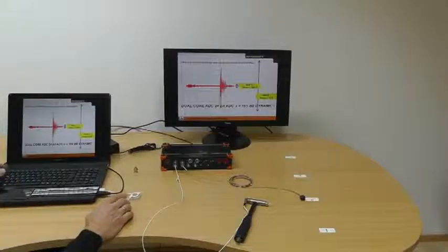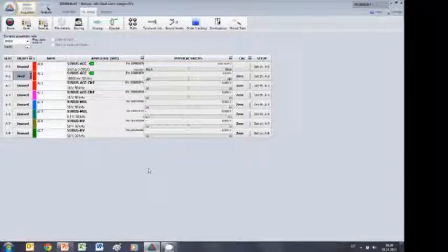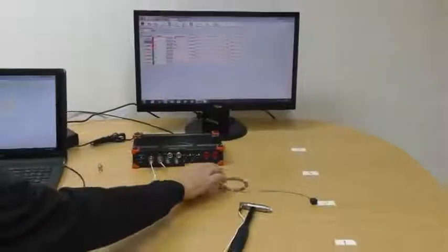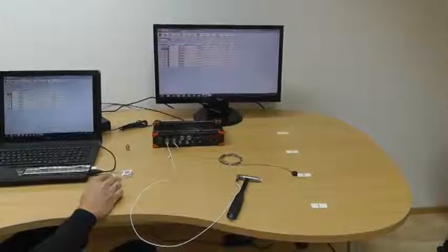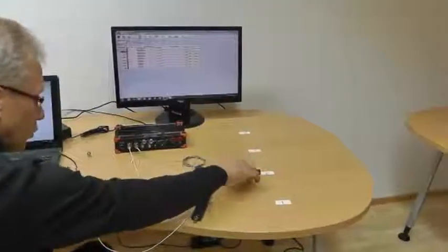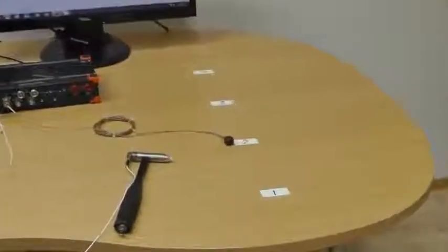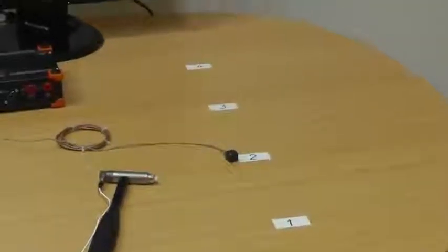To show that as a demo, we go to Dewesoft and show this as an example. How to demonstrate it: I have connected two ICP sensors on channel 1 and channel 2, and I take channel 2, where the one sensor is just fixed on the table, and show you now with the measure mode the very small little signal.